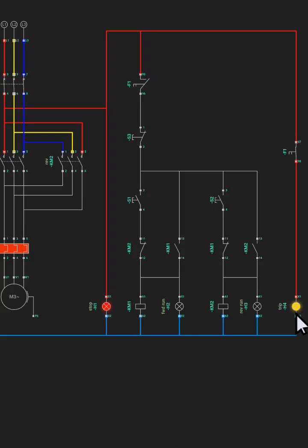So that's what could cause the overload to trip: the motor draws a high current as a result of the load connected at the rotor side being excessively large. If it's a conveyor belt, maybe the belt is stuck somewhere, or there is a jam. All this can cause the current of the motor to rise.